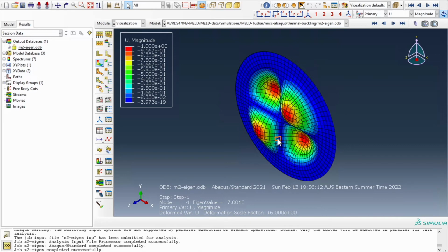Okay, so why are these eigenvalues and modes important? From this we can understand the basic buckling modes of the problem, how it may buckle under different loading conditions. Because when we subject the structure to any realistic loading condition, if it is predominantly a compressive one, it may buckle, and the actual deformed shape may consist of multiple buckling modes of the structure, right?